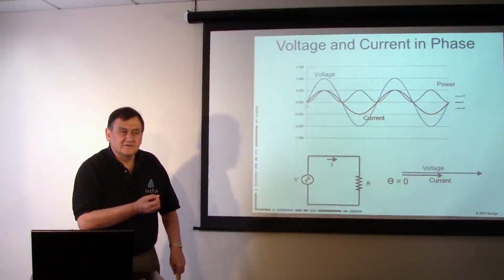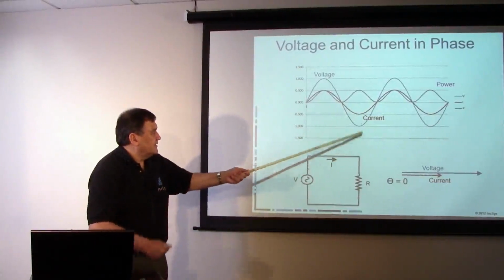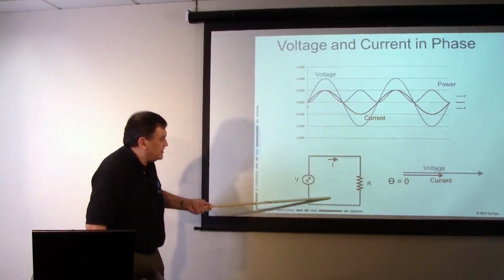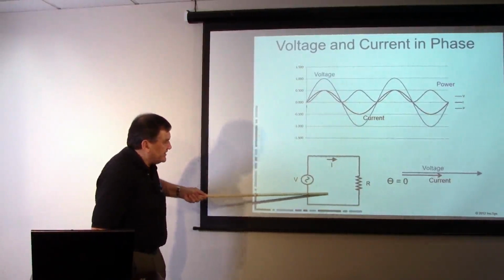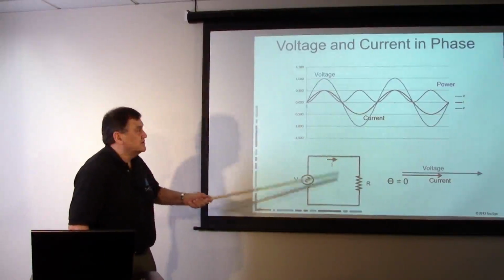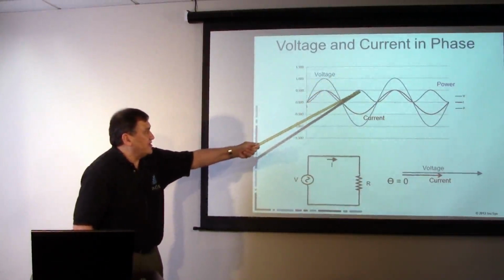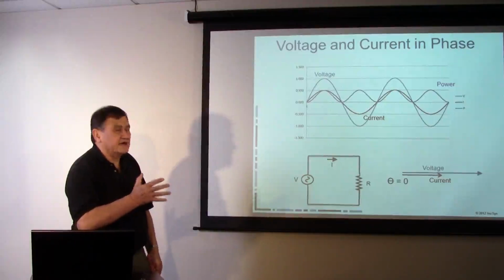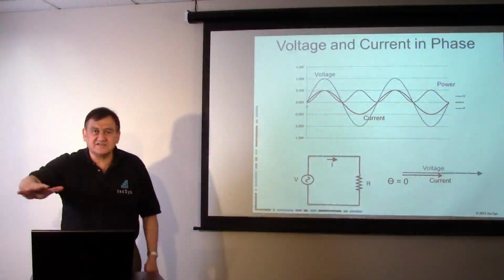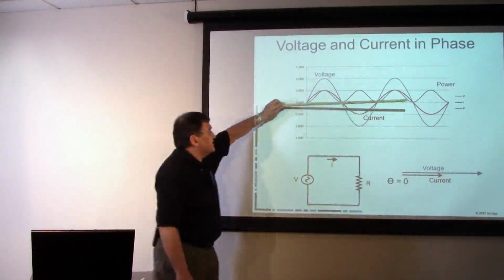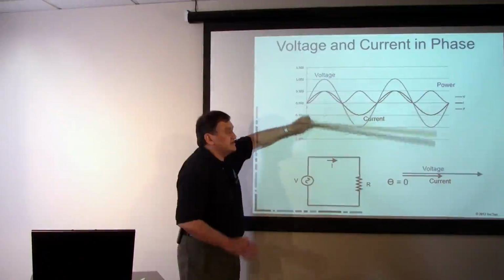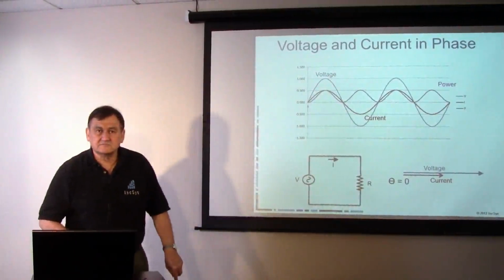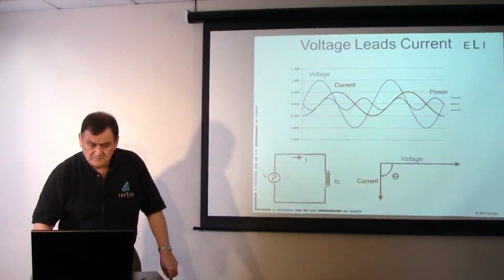Okay? So we've got an AC load, and even though we get positive power as the current flows this way, we also get positive power as the current comes back this way. So by definition, our power waveform is peaking even when these two are negative. So it's actually going at 120 cycles a second. And there's a net average value. The net average value is right through here, and so we're getting a dissipation of real power in this circuit.